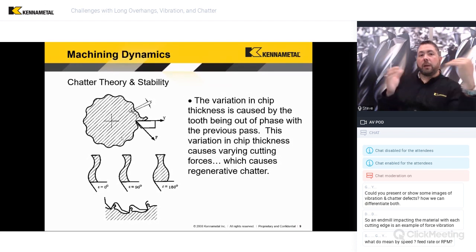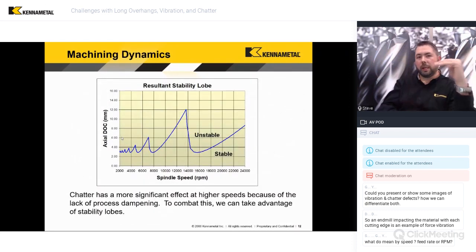If it's very high, for instance, we're really in trouble because it doesn't matter what we have. At some point, we're moving that tool more than we have programmed for a depth of cut, all right? I'm speaking in relative terms here, so forgive me a little bit. But that's where we start to see the bottom level where things are stable at a lot of RPMs, versus the top level where we eventually top out even in one of the better and more stable parts of the curve.